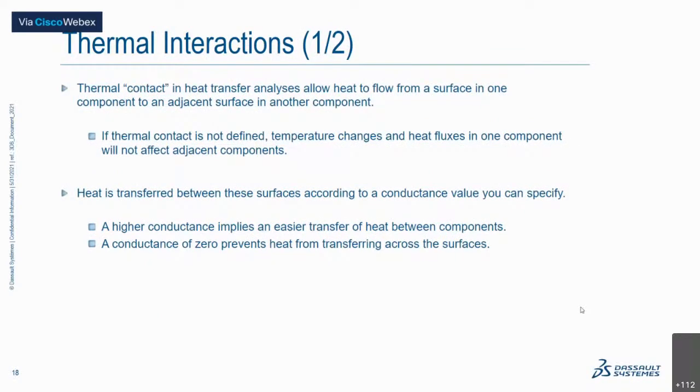Similar to the structural interaction that we do for structural simulation, that is load being transferred among the components on which the load is acting, in a similar way, thermal contact is something that we need to establish in order for a simulation to be much more accurate. If there's a heat transfer and two components are close to each other, there will be some heat transfer that occurs between them. So to do this, we have the thermal contact, which is to be established here.